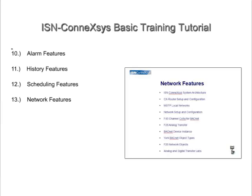Then we move on to Feature 28, Analog Transfer, where we prepare to transfer a value, possibly a temperature or pressure, over the BACnet network to be shared with other BACnet compatible devices. Then we set up the BACnet device instance, which is a parameter required to do the BACnet transfers. We cover then the York BACnet object types. What type of data in our controller can we share with other BACnet compatible devices? Feature 20, Network Objects, is covered, and then we have an analog and digital transfer lab.